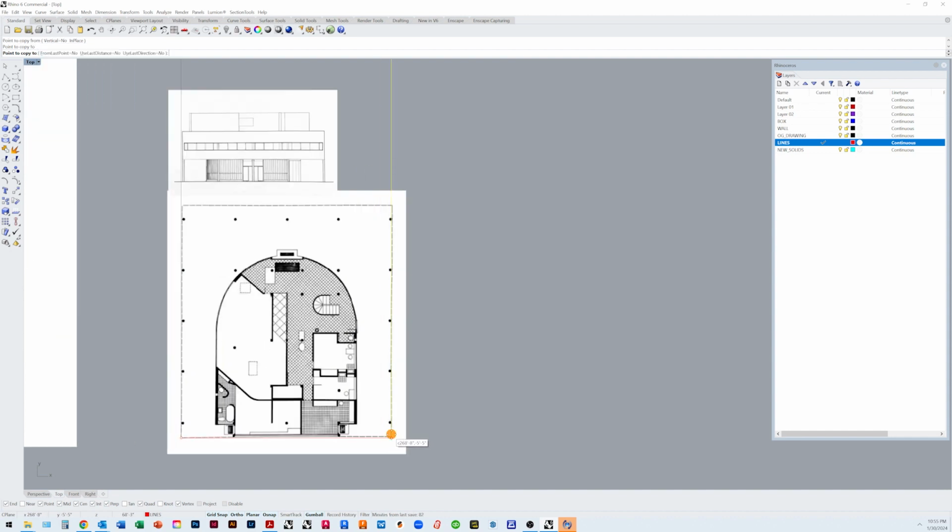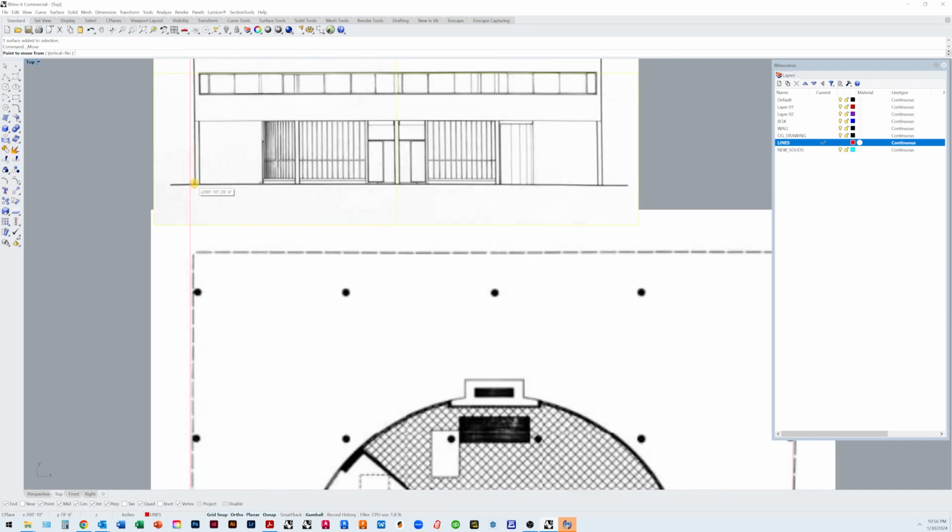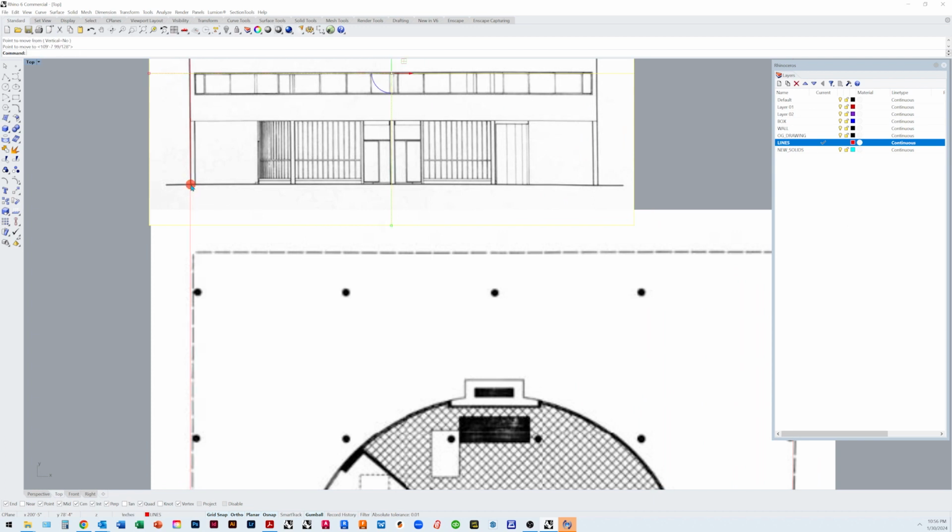So I've got 2 lines here, and those hit the sides of those 2 columns. Here's a column and there's a column. Here we can move this drawing so that this column lines up with the edge of that line, and then watch how we can scale this one. We type scale. This is our base point. Click here.